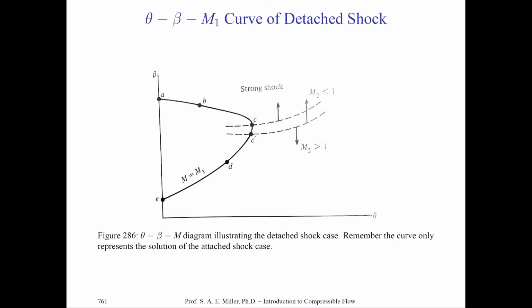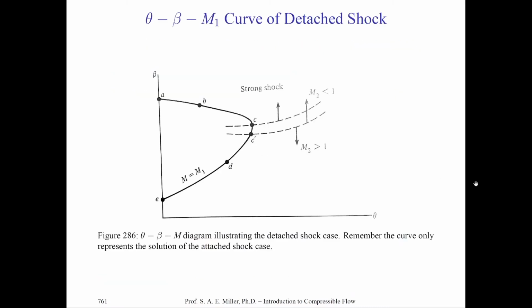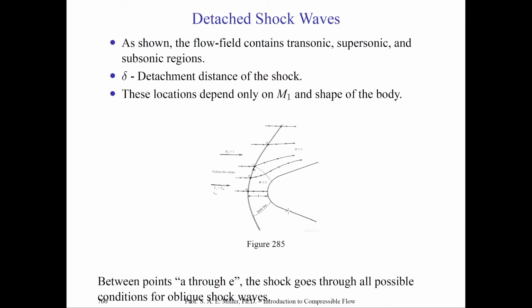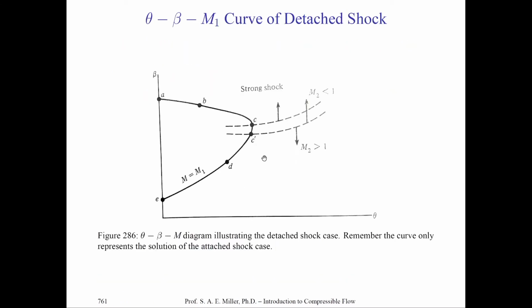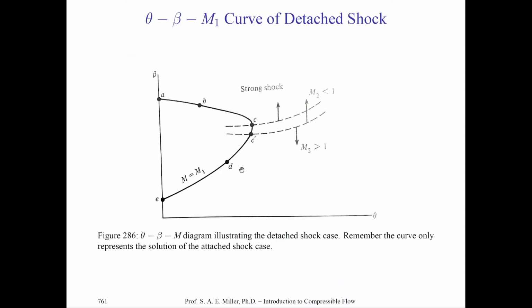And the whole oblique shockwave family, even though it's a strong detached shock and not attached to the vehicle, can be translated to the theta-beta-Mach number curve as we showed in this particular diagram. In reality, for this particular incoming Mach number and turning angle of 90 degrees, there's nothing that falls on the chart, but we can interpret the actual shock wave and its properties across it with the same theta-beta-Mach number equation and diagrams.